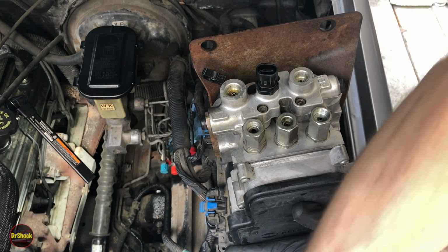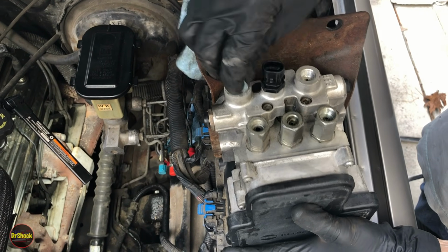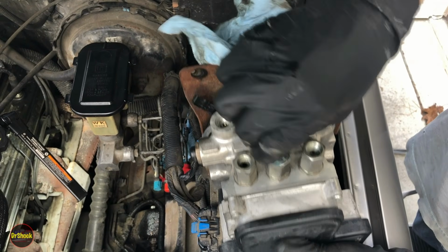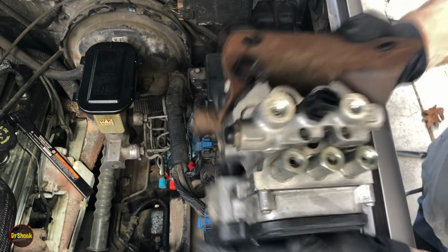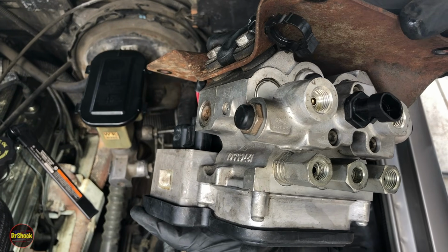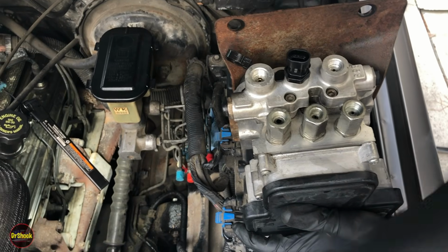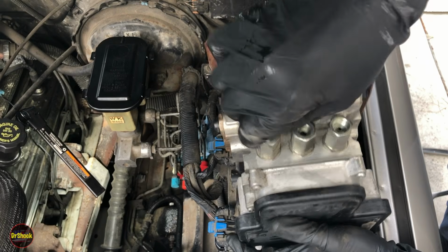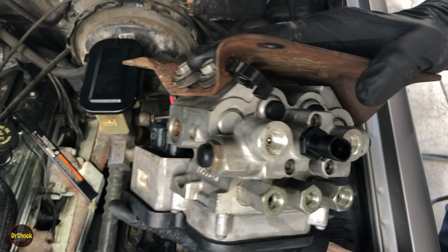All you want to do on here is just take a real quick clean rag, get some of this brake fluid out of here, spread some around on the threads, help things go in better, and then just take a quick gander, make sure you don't see any dirt or debris. Sometimes there's some discoloration. You can give that a quick test just to confirm this discoloration. If you give it another rub and it doesn't move or change, then it's discoloration.